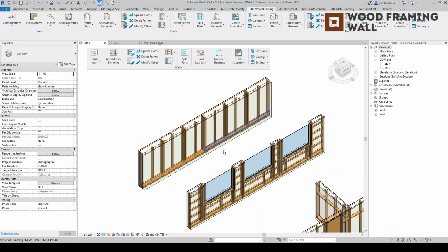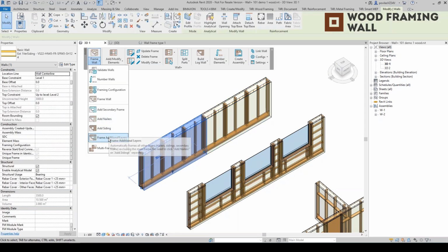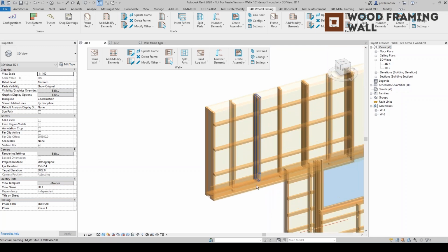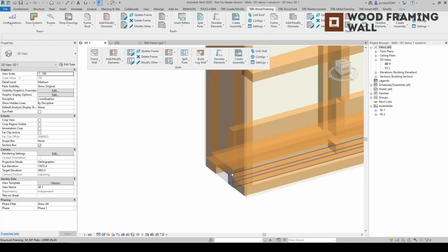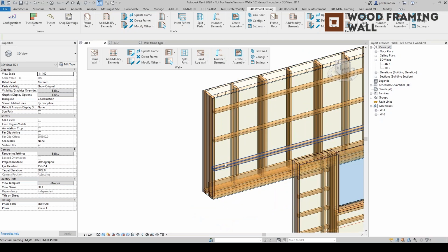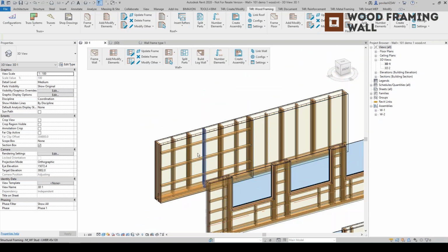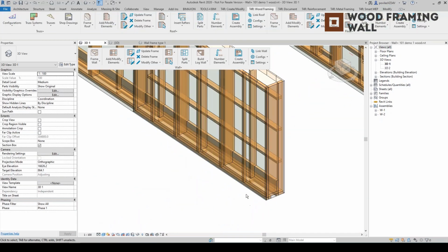Okay, so those two wall segments are framed. We're going to add, if I go for frame additional layers, you should recognize all additional layers I haven't framed yet. Okay, so this wall has different kind of variation for a base plate. We have noggings distributed throughout the height of the wall, and secondary frame on the side, actually on both sides.